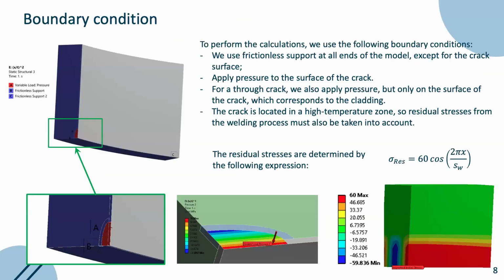To perform the calculation, we use the following boundary conditions. We use frictionless support for all ends and apply loads only on the crack surface. Also, when the crack is located in a high temperature zone, we must also take into account residual stress.